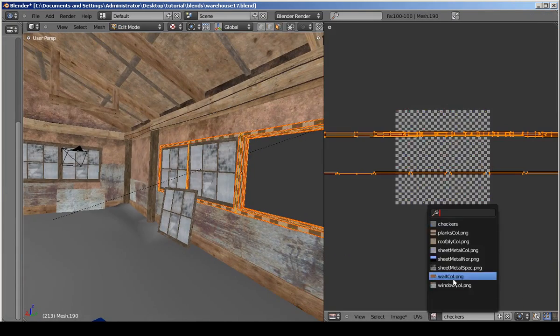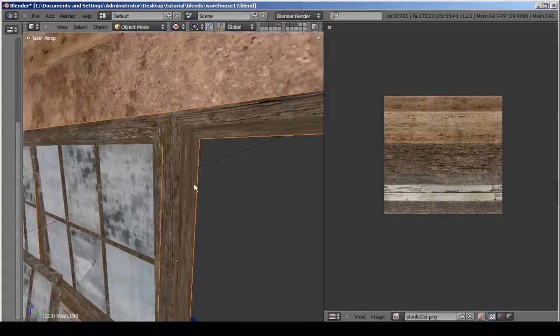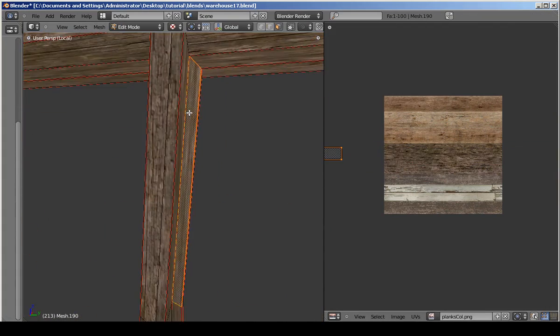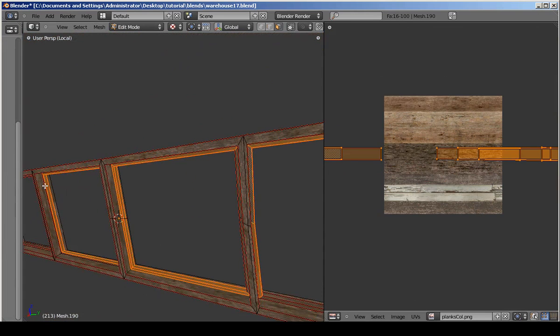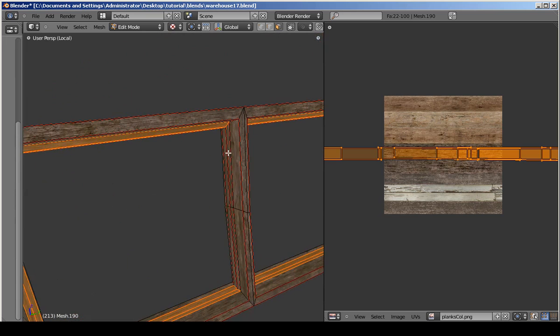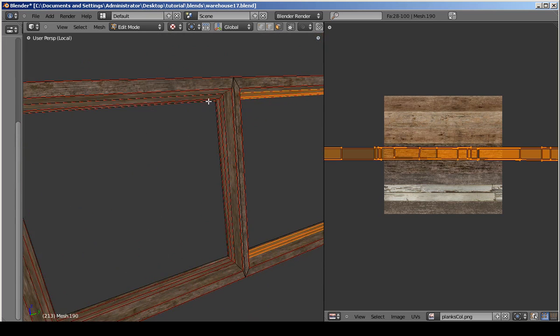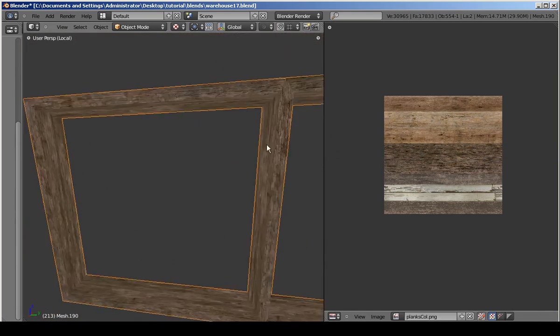When I don't need it to visualize things, I turn alpha off on materials, because at least for the time being, if you have alpha turned on and you're rotating the scene in GLSL mode, everything kind of flickers and blinks, and it gets really annoying after a while. So when I'm not using or visualizing things with alpha turned on, I turn it off.